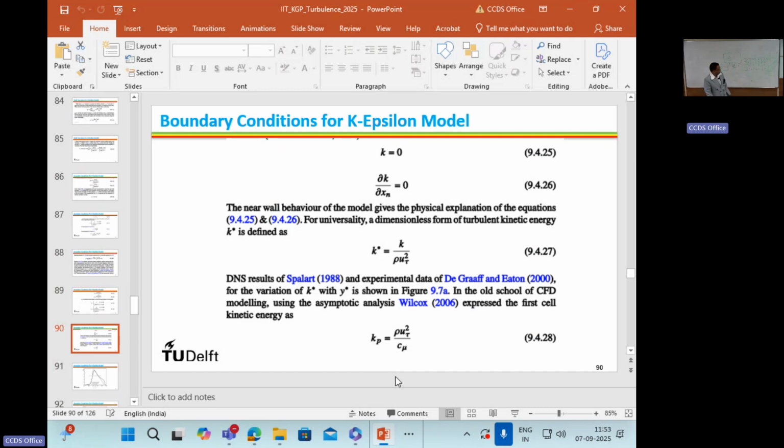These are my solid boundaries. Once I am in the high Reynolds number formulation, the matrix solver solves velocity only for the internal cells, not the cell adjacent to the wall boundary. Where do they get the velocity for the wall boundary? That we just discussed.